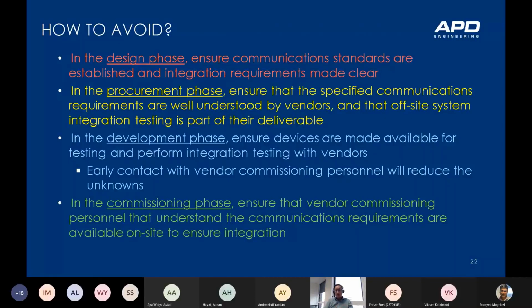Well, here are some suggestions to avoid the types of issues I mentioned earlier. In the design phase, ensure that communication standards are established and integration requirements are made clear. In the procurement phase, ensure that the specified communications requirements are well understood by the vendors, so work with the vendors, and that offsite system integration testing is part of their deliverable. If you can get that through, be nice. In the development phase, ensure devices are made available for testing and perform integration testing with vendors wherever you can. Early contact with the vendor commissioning personnel.